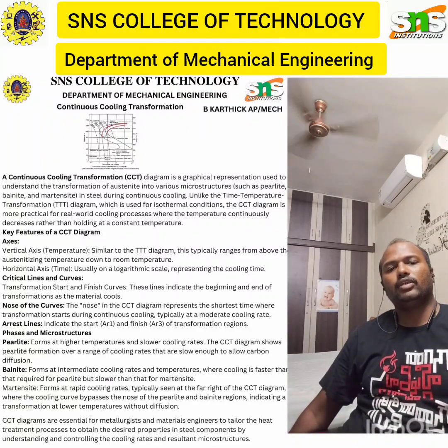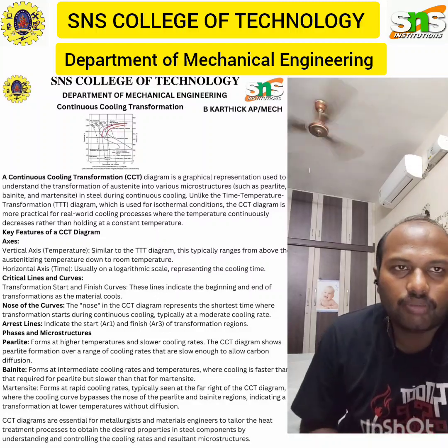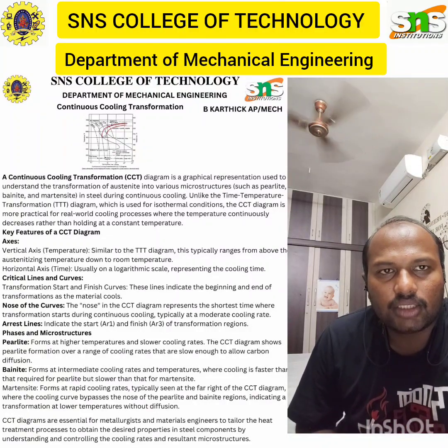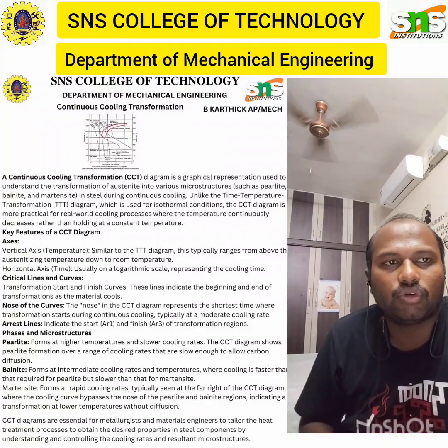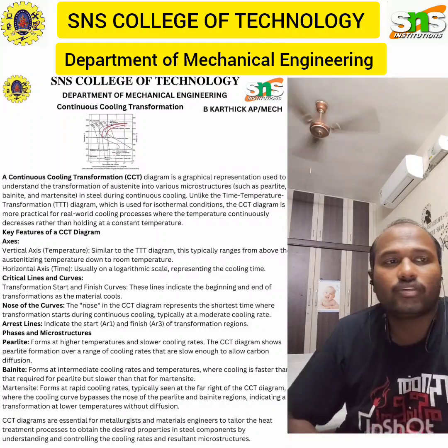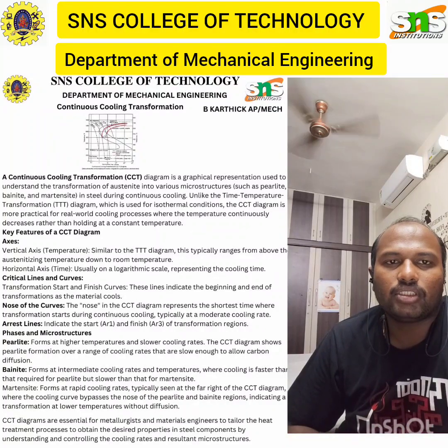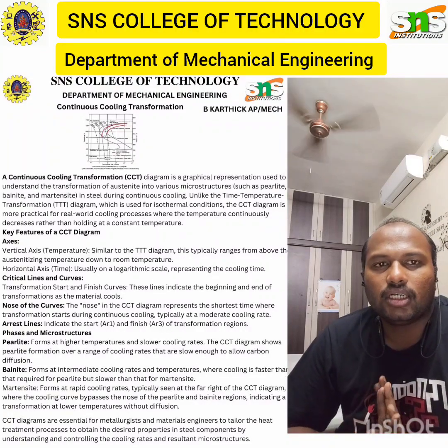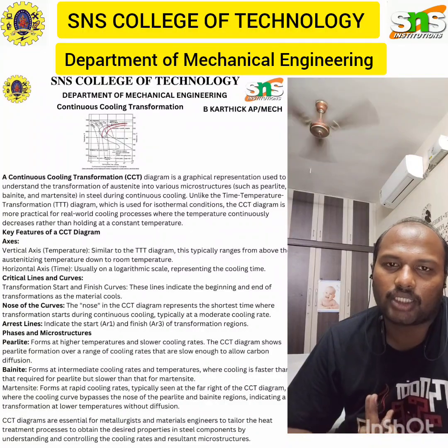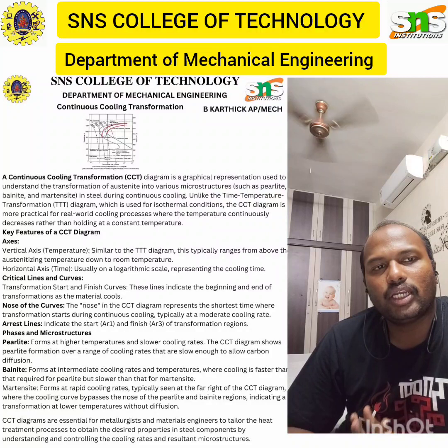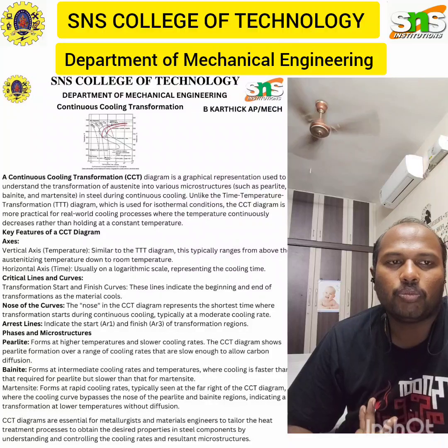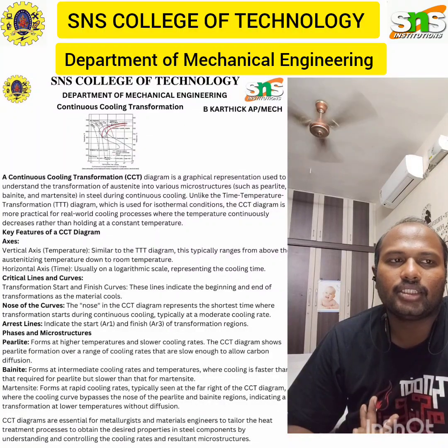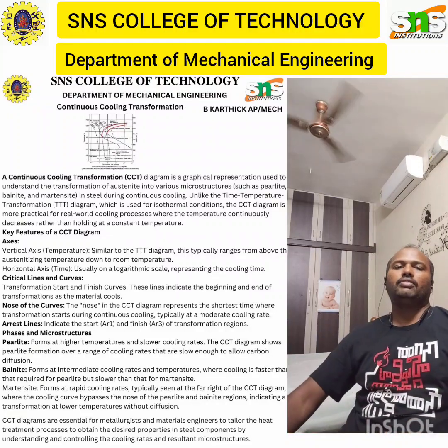When we take the phases and microstructures, the first one is pearlite phase, which forms at high temperature and slow cooling rate. The CCT diagram shows pearlite formation over a range of cooling rates that are slow enough to allow carbon diffusion. The second one is bainite, which forms at an intermediate cooling rate and temperature, where cooling is faster than that required for pearlite but slower than that of martensite. Martensite forms at a rapid cooling rate, typically seen at the far right of the CCT diagram, where the cooling curve bypasses the nose of the pearlite and bainite region, indicating the transformation at low temperature without diffusion.